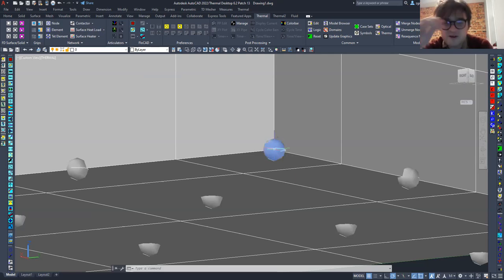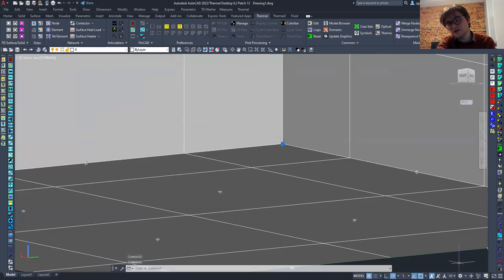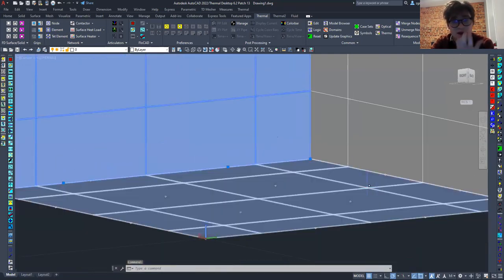If you kind of click your mouse around in there, you'll notice that there are multiple nodes. So you see how it highlights, but there's some node that's not connected. If you think about what we did here, we actually have 3 nodes sitting right on top of each other. And what we want to do is merge all 3 of those together because we want this to be one continuous surface, we want heat to be able to travel through this surface and up into this one. And I get the feeling that if we don't do anything here, then we might have a problem. But to be honest, I don't know. I don't even know if that's perfectly accurate. We might be able to just run the simulation without doing that, and it might just work.